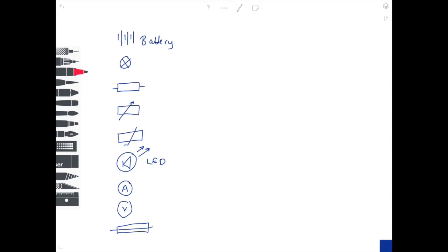Remember, if you're asked the difference or the advantage of using a circuit breaker as opposed to a fuse, is that a circuit breaker is much faster and easy to reset. Why? Because look at the fuse, the wire is going to melt, and so you're going to have to replace the whole thing before you get your circuit working again.